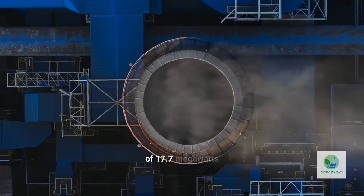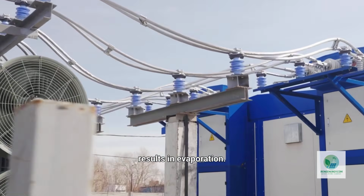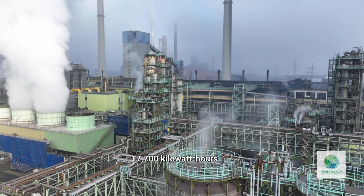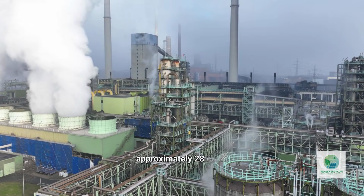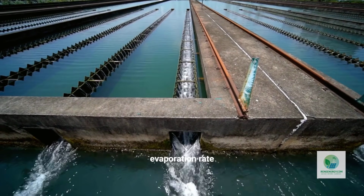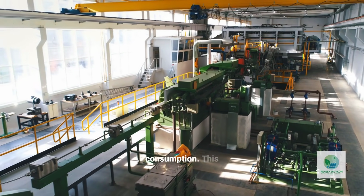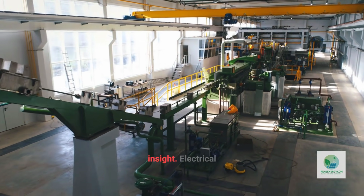Heat rejection of 17.7 megawatts using wet cooling results in evaporation. A common engineering approximation is 1.6 liters of water evaporated per kilowatt hour of heat rejected. At 700 kilowatt hours per hour of thermal rejection, evaporation equals approximately 28 cubic meters per hour. Notice that this evaporation rate exceeds stoichiometric reaction water consumption. This reveals a fundamental systems insight.